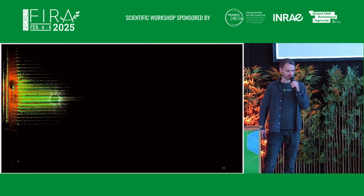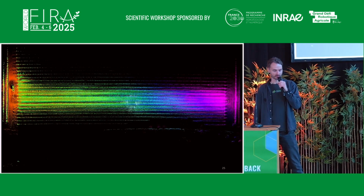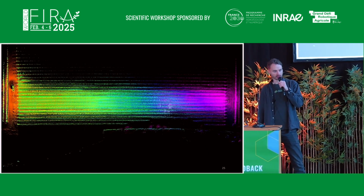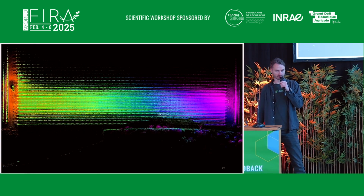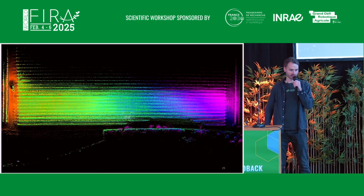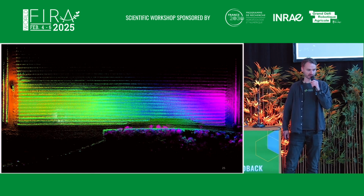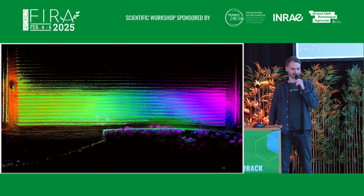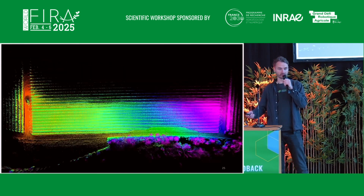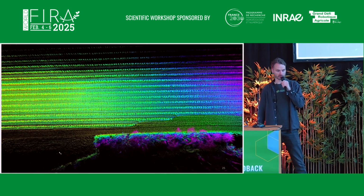We did that also in an orchard. So here's the orchard. The machine can drive along these rows without GPS and RTK, which is often a problem when the trees block the signals or shadow them a bit. So it's much more robust than just using GPS and RTK, where the machine may need to stop. Of course, you can have some reactive row following, but this is a more universal approach for navigation.